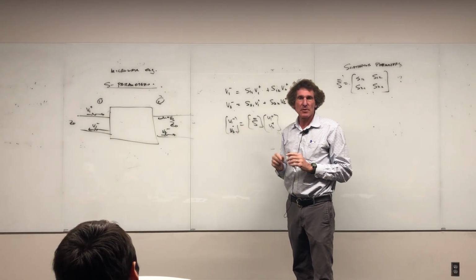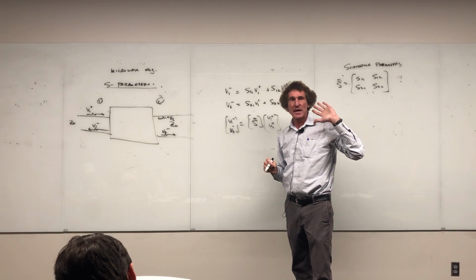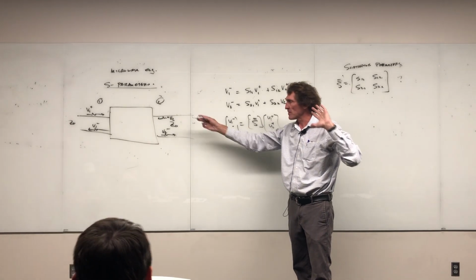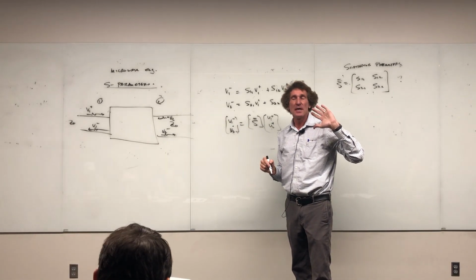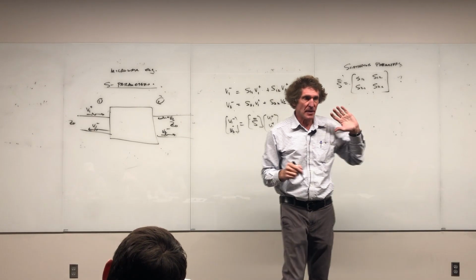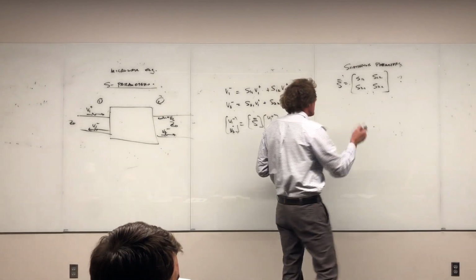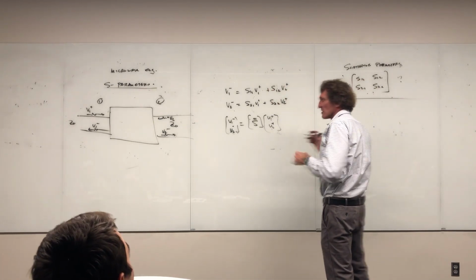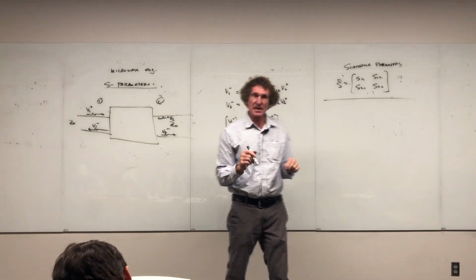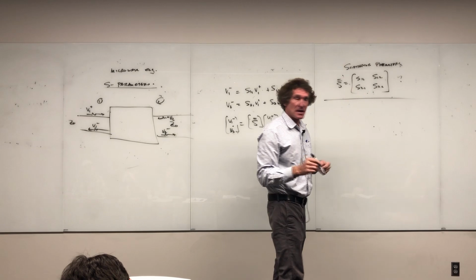Has anybody used S parameters here? This is how all high frequency work is done. When they characterize amplifiers, or filters, it's always with S parameters, always. A lot of times they're given in dB, but it's very common and you see it everywhere. Now, when you have S parameters, the first thing you've got to do is learn how to calculate them. You can't design anything until you realize how to actually go through an analysis.